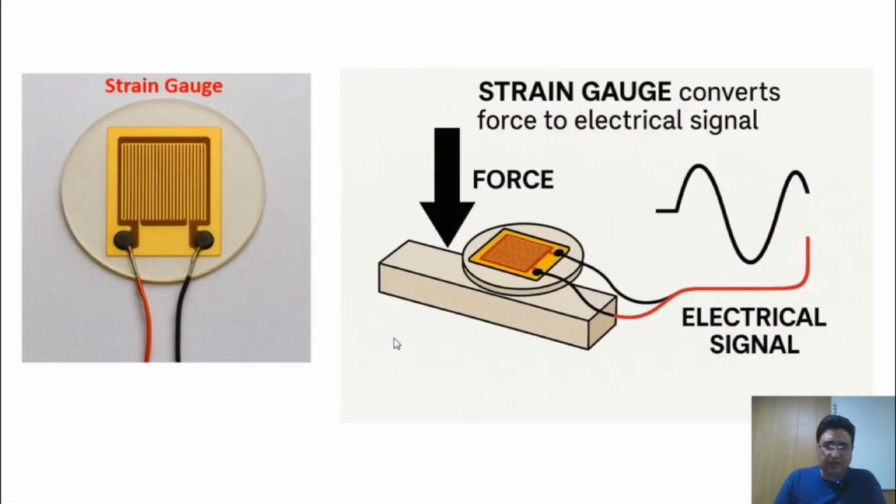A load cell typically consists of a robust metal core and a specialized material called a strain gauge, which is precisely placed on this metal core. When we carefully place the sensitive strain gauge onto the robust metal core and then precisely apply an external force to this solid core, the mechanical force we apply here is accurately converted by the highly responsive strain gauge into a measurable electrical signal. Subsequently, based on this electrical signal, we can readily observe and monitor the weight changes displayed on a connected digital display unit.